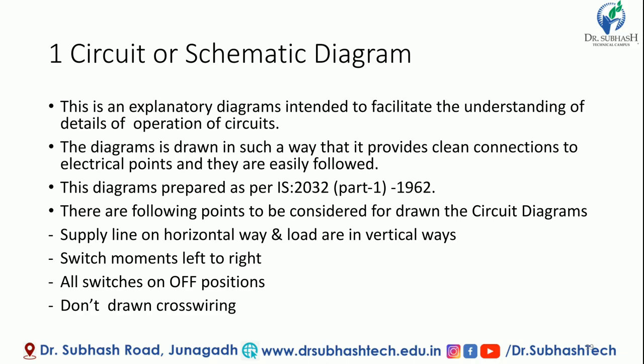There are the following points to be considered for drawing a circuit diagram. First, the supply line is horizontal and the loads are vertical, which means you should always draw the supply line on the horizontal line and loads on the vertical line. Switch movements are from left to right.